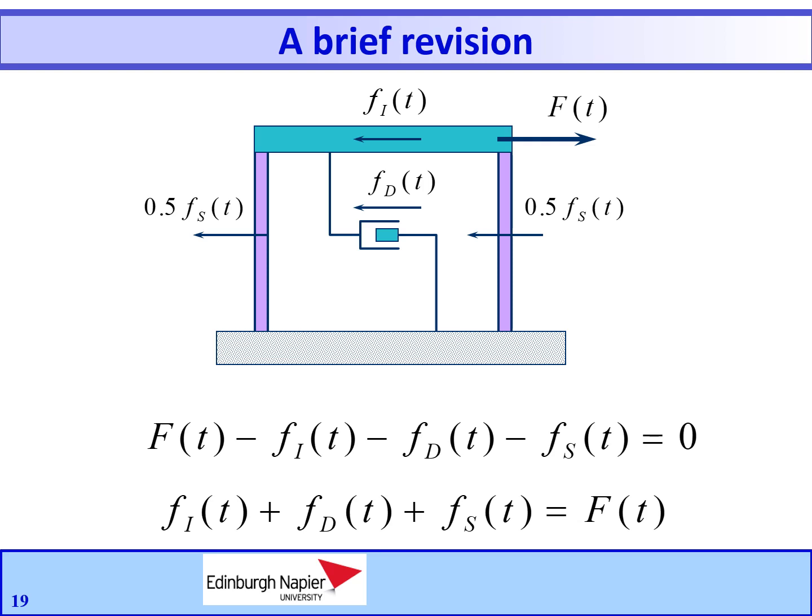So have a look now at this idealized one-story frame as introduced earlier, that is subjected to an externally applied dynamic force in the direction of the degree of freedom u. Both the force and the resulting displacement of the mass vary with time. So we can derive the differential equation governing the displacement u as a function of the time by applying Newton's second law of motion.